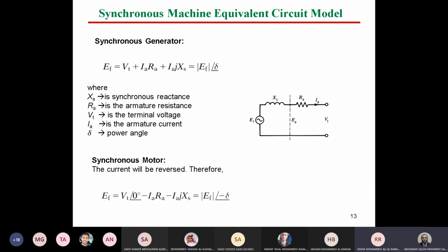Doctor, is this for self-excitation? What do you mean by self-excitation? I mean, does this model represent general synchronous machines, or a specific kind? It's a mathematical model for the cylindrical type synchronous machine, for all types of excitation, either brush or brushless. Okay, and this is for cylindrical type, am I right? Cylindrical type, yes.